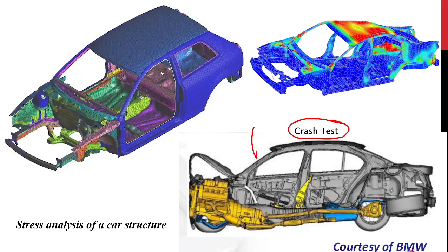And then they will also look at the A pillar, and then look at the B pillar and C pillar. Is there any deflection of the A pillar? And then the front of the bonnet, if it is shaped like this, it is good. If it fails, the bonnet goes inside like this, goes inside there. This is a fail, it enters the passenger space. The engine drops, but it does not enter the passenger compartment.